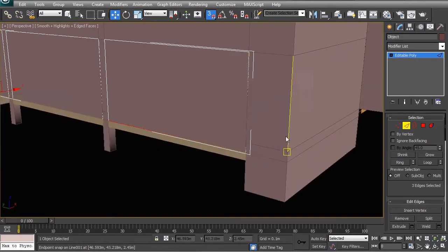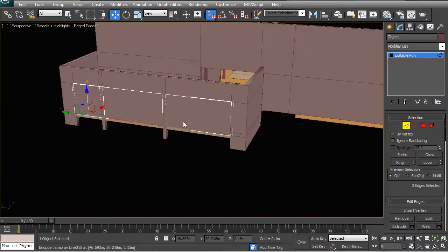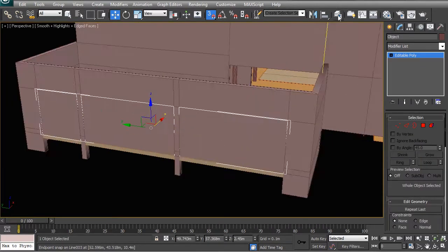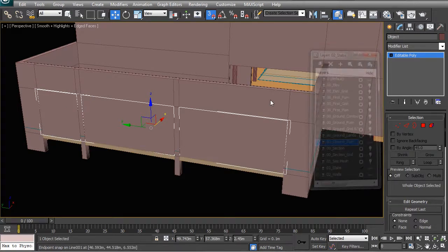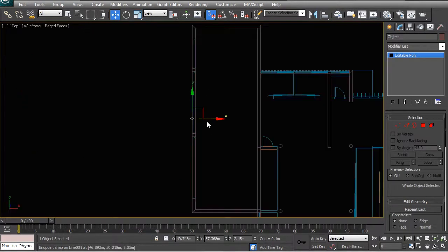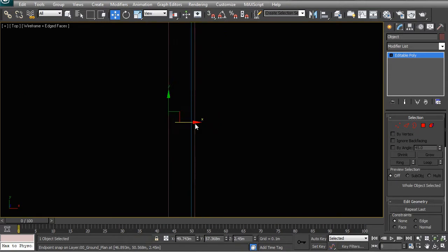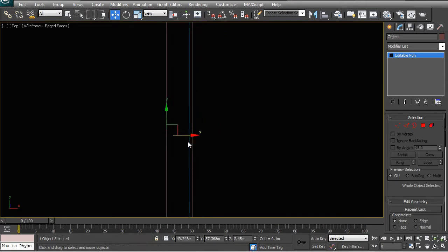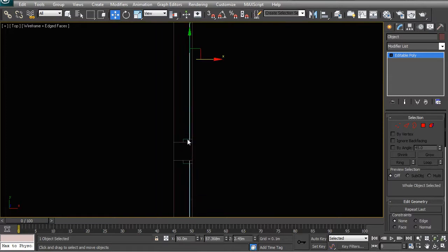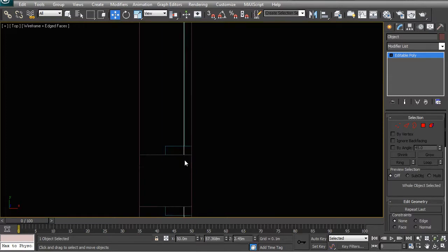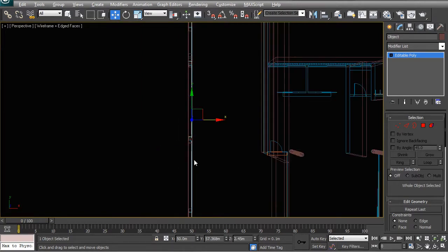It's much easier to have this, and you can start to see why right now. The next thing you want to do is, with your plan now turned on, move your garage doors into the correct place. So you can take that object and move it back into the location where your doors are actually happening. You'll see that right now your object is going right to the end, but we have the situation where we have frames around our garage doors, as you would imagine.